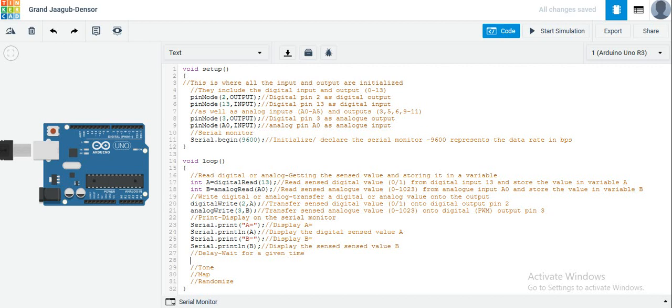So it's just a simple command. You just do delay, and please note that in the syntax, there's no caps. Then you put 1000. Whatever is in brackets is the time in milliseconds. So delay, wait.